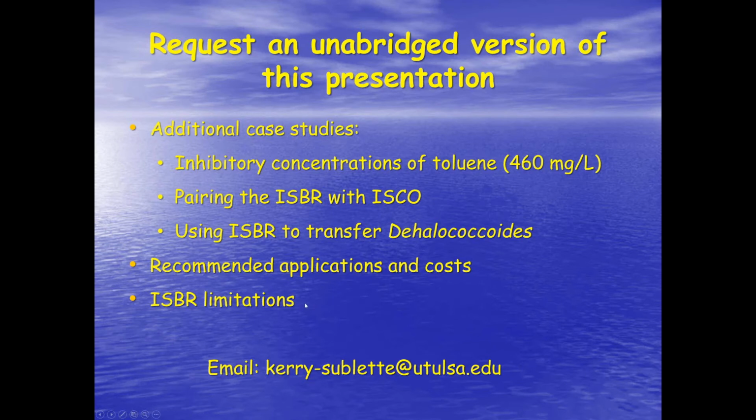And one of those limitations I would like to tell you right now, and that is that the ISBR basically works by inducing that circulation process that we talked about. So the ISBR must be at all times fully immersed in groundwater. If the water table drops and you expose the top of the in situ bioreactor, then you're not going to have that circulation and the in situ bioreactor will cease to function. So we need to keep that in situ bioreactor completely covered with groundwater at all times, and if we do, it'll be fully functional.